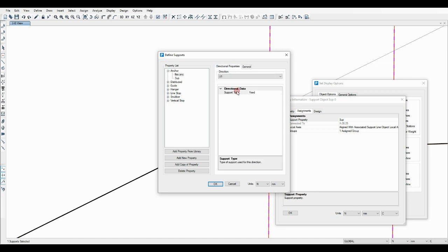So U1 being the radial direction. Then we'll have U2 and U3 being shear directions. We'll normally leave those rigid. R1 torsional is pretty rigid. Let's move to R2, the circumferential direction. Give that a stiffness, Newton millimeters. Let's change that to meters. It's pretty odd the way it shows joules, which dimensionally is the same as Newton meters. So let's put that one in. Newton meters per radian, and R3 being the longitudinal direction.